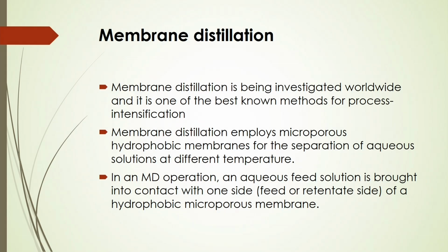Now, since we are talking about membrane distillation for process intensification, this membrane distillation is being investigated worldwide, and it is one of the best known methods for process intensification. And membrane distillation employs microporous hydrophobic membranes for separation of aqueous solutions at different temperatures.